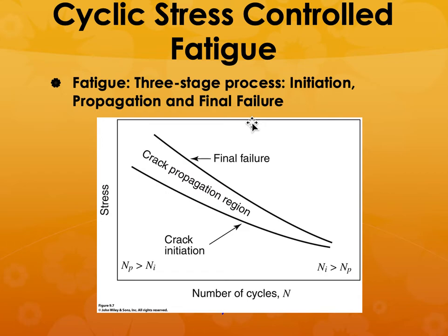Fatigue is typically a three-stage process. First, the crack initiates, then it propagates, and then the sample cross section can no longer take that load and it will fail catastrophically. So typically